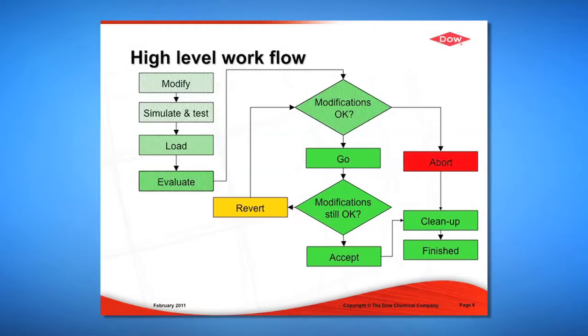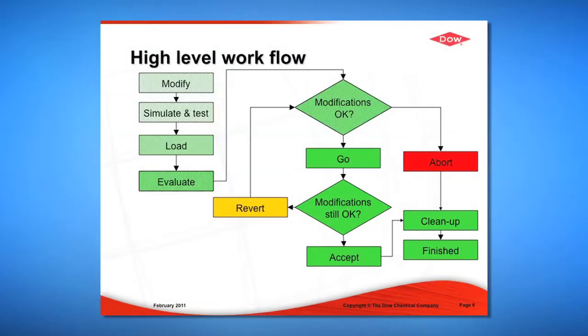You know, we hear the terms load, evaluate, go, as opposed to load and go. That evaluate step in the middle is really critical. So you make your modification, you do some simulation, some offline testing, some confirmation of the change you want to make, and then you load it. Well, in a conventional system, once you load it, it's loaded and it's running. In this case, you have these extra steps in the middle.